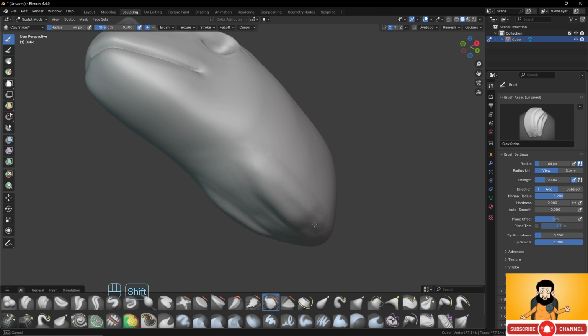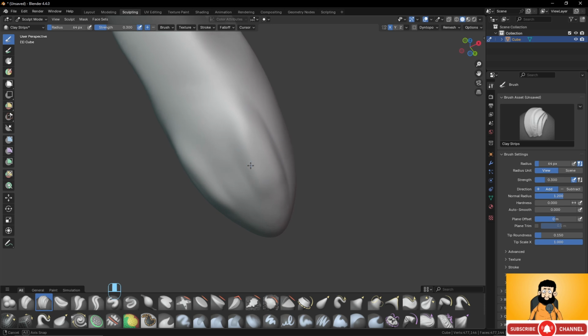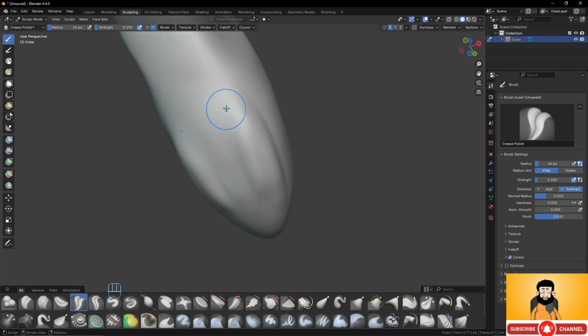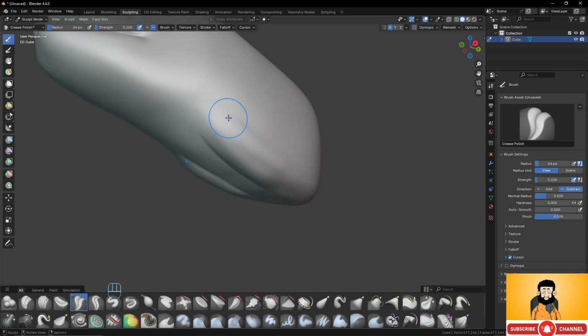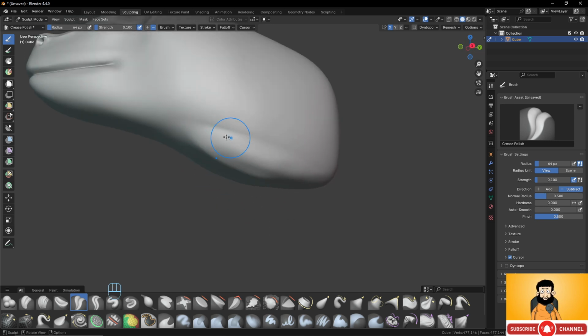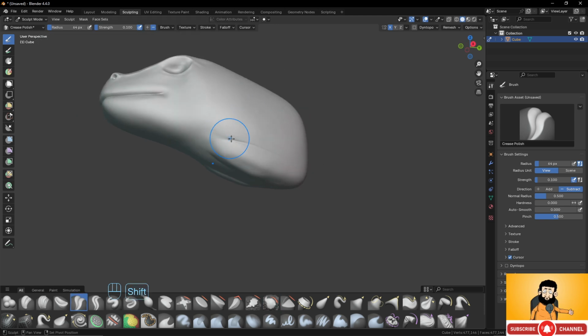So you will just create the basic shape of your muscle over there. Okay, and you can even come back with the crease here to increase the sharpness here around the muscle. You can see that it works pretty well, and you can even make a direction more on this muscle like this.